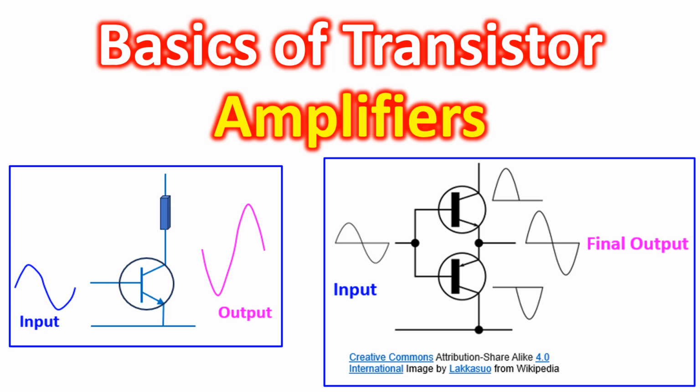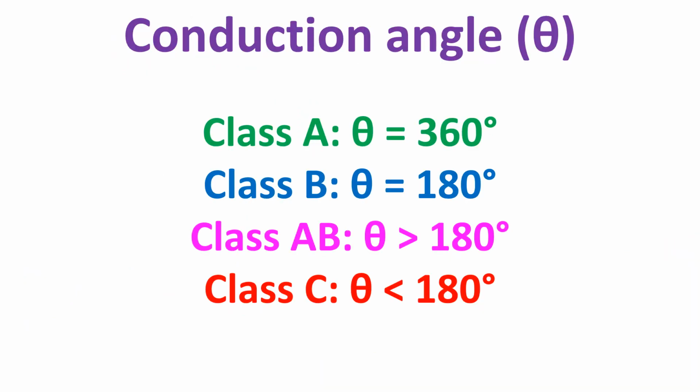While these classes are for linear amplifiers, there are also Class D and E for switching designs. Classification of the linear designs is based on the time period during which the active amplifier device is passing current, expressed as a fraction of the period of a signal waveform at the input. This metric is known as the conduction angle theta.